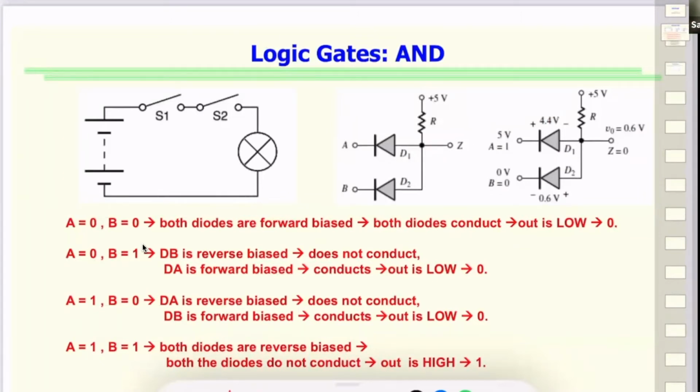On desktop computers, it used to be 0 volt and 5 volt, but now in the smaller, portable devices, low is not always zero. It is some baseline, and high can be 1.1 volt or 1.2 volt. So we just stick to low and high instead of actually putting the voltage. But we do have a notion of what kind of voltage is there on the power supply and what kind of voltage is shown. For example, here we have shown 5 volt and 0 volt. So two discrete levels between those two.